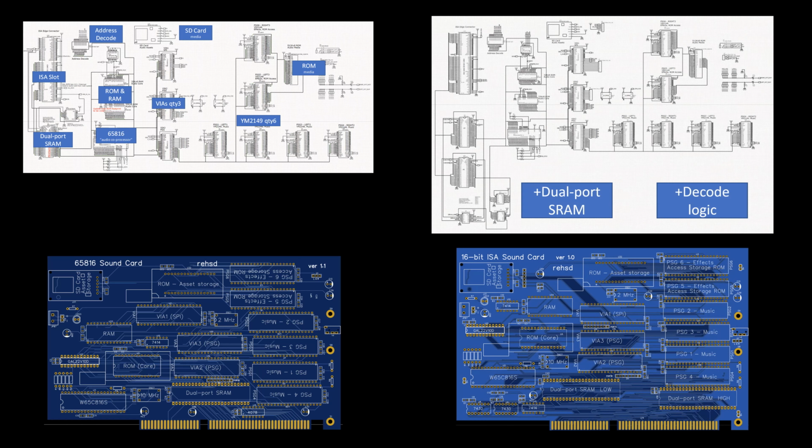So I've done some of these changes, and probably the most significant is this extra dual port RAM to support a low byte, high byte configuration. On the old schematic to the left, I just had a single dual port RAM IC, but as I look to the right, I now have a pair of them. If I take a look right here, you'll see that there's now a low and a high. You probably can't read that, and I'll zoom into the actual schematic after a little bit. But I have a pair now so that I can have the low byte and the high byte.